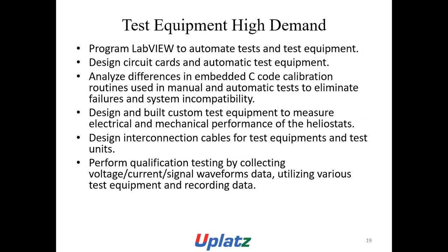Program LabVIEW to automate tests and test equipment, design circuit cards and automatic test equipment, analyze differences in embedded C code calibration routines used in manual and automatic tests to eliminate values and system incompatibility, design and build custom test equipment to measure electrical and mechanical performance of the HelioSat, design interconnection cables for test equipment and test units, and perform qualification testing by collecting voltage, current, signal waveforms, and data, utilizing various test equipment and recording data.